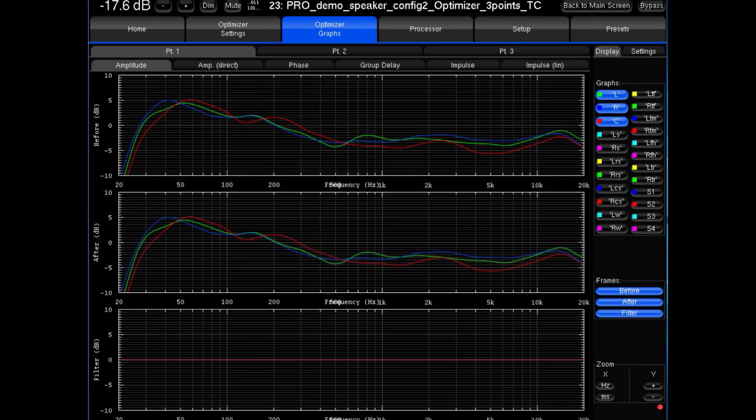And what happens with a high directivity speaker like ours is it goes, wow, look at all that mid bass and bass energy, and it either endeavors to take that away, or usually what it does is it raises up the level above 500, 4 dB or 5 dB or something, in order to make a more flat curve all the way across the entire sonic spectrum.